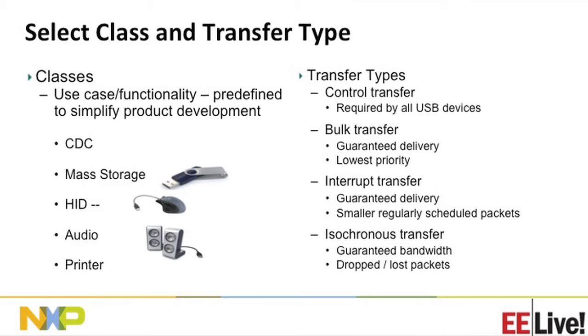Isochronous transfer is a guaranteed bandwidth so that information can be delivered as soon as possible, which is mostly used for video and audio devices where latency is not allowed. However, isochronous transfer doesn't have error tracking. Like you drop a little bit of the video or sound, but the purpose is to catch up the speed.